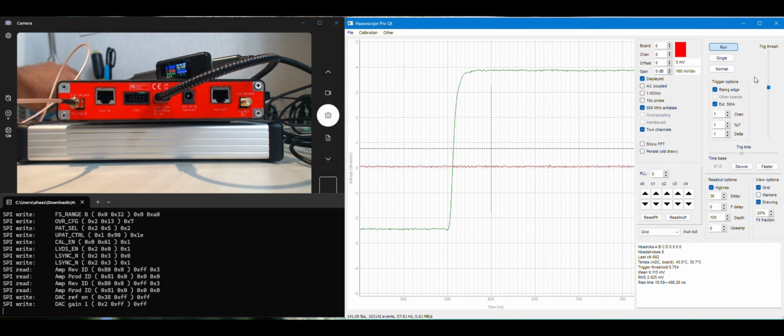If we turn it down to 2 volts, it stops. So you really have to get it up to about 2.5 volts, and it'll be fine. And you could put in anything up to like 5 volts there. It's not going to really cause it any problems. I wouldn't go too much higher than that, but what are you going to have that's more than 5 volts, really?